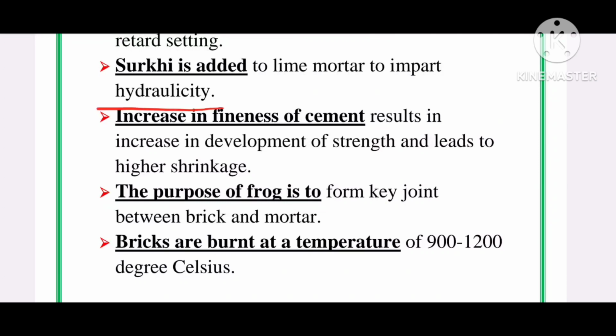Next point, increase in fineness of cement results in increased development of strength and leads to higher shrinkage. As the fineness of cement increases, strength increases and shrinkage also increases.